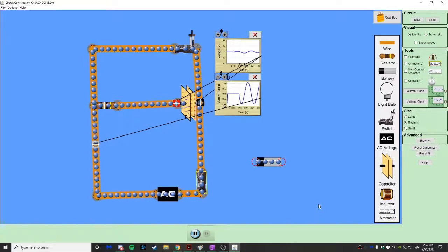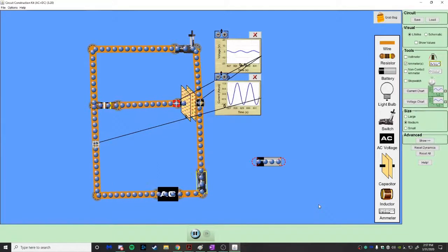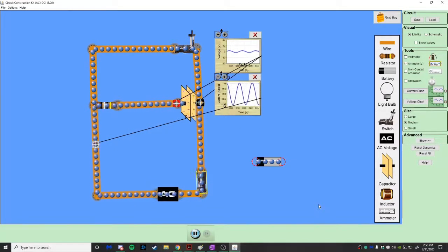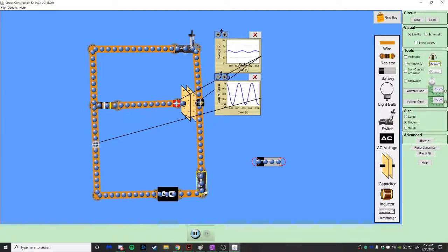Okay. So what you're looking at now is what a capacitor does inside of a circuit that has an alternating voltage. Can you see how it behaves quite a bit differently now? It doesn't really stop the charges from flowing. It acts kind of like a spring that absorbs the energy of the current and then reflects it back in the opposite direction. Can you guys see that happening? Can you see how one side's positive and then it becomes negative and then positive and then negative? Does this motion look like something you guys have seen before?